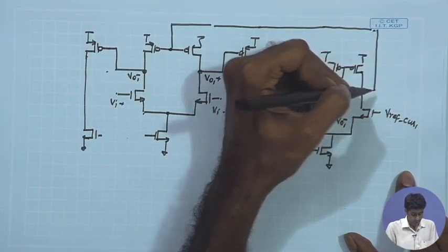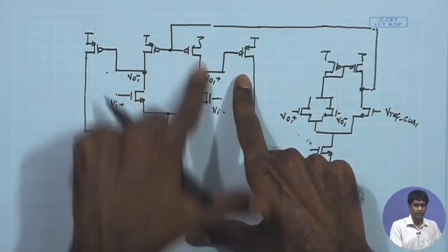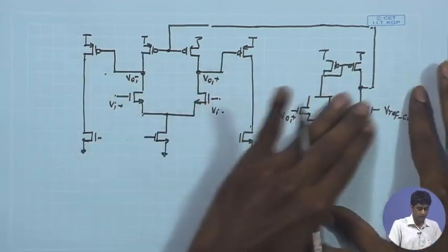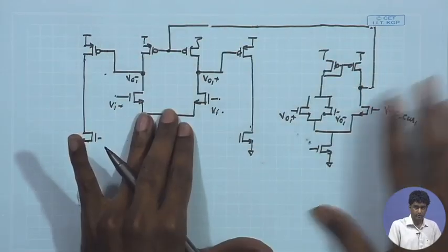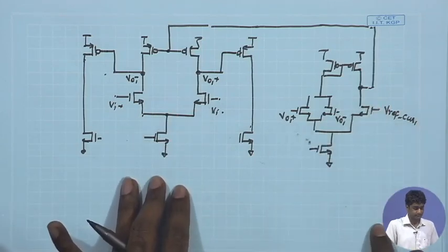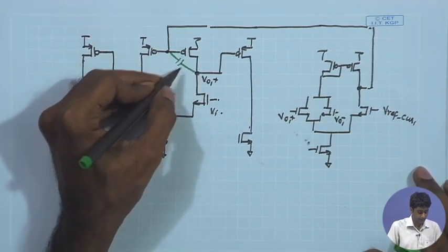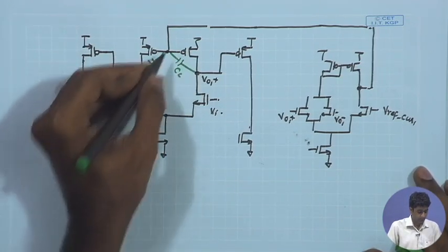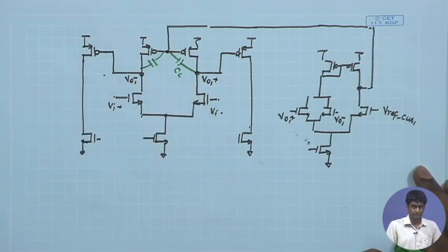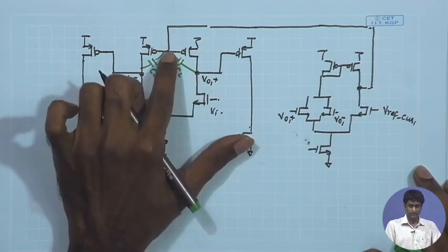And this is what we did in the beginning, while we looked into the common mode feedback of a single stage differential amplifier in isolation. So, we have already analyzed this particular configuration, where you have the single stage diff amp compensated by an error amplifier, and we looked into the compensation scheme and suggested including coupling capacitors between the gate of the PMOS transistors and the output of the first stage, which is effectively going to give us overall mirror multiplication at this point.